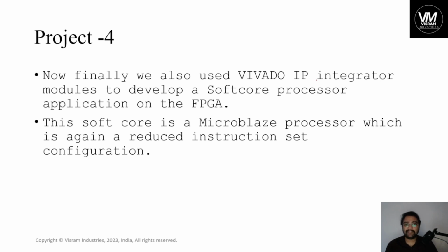This again takes IP modules that are already available. IPs are intellectual properties developed by different vendors, and we collect those IPs together and develop a design using those IP modules, which is mostly done by EDA automation. Hence we can develop our application within a few hours, and check the functionality as well. Then with the MicroBlaze processor, we also tried to test the hello world program in C programming, not HDL programming.